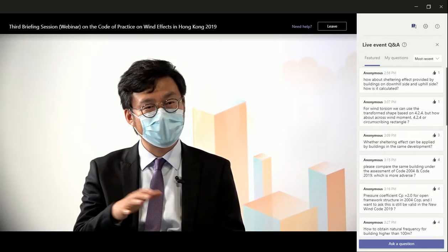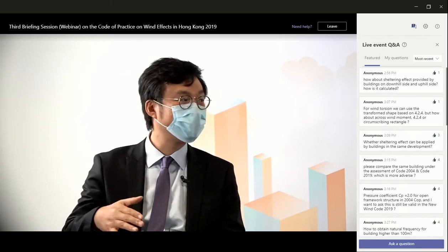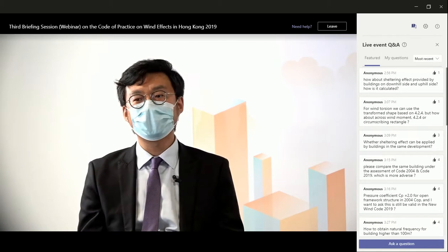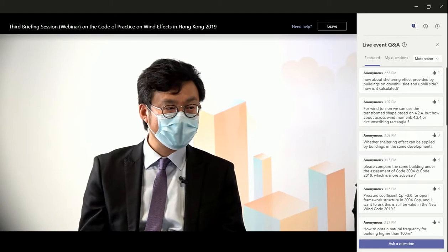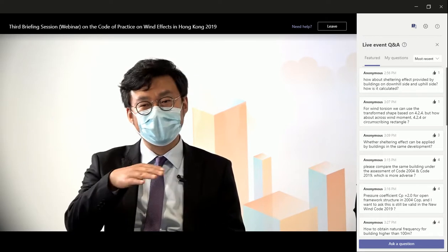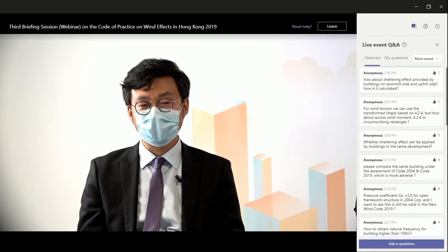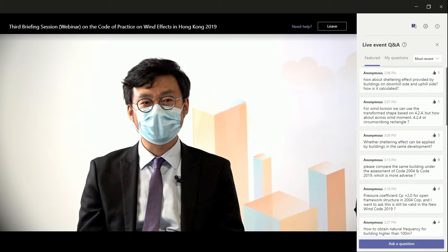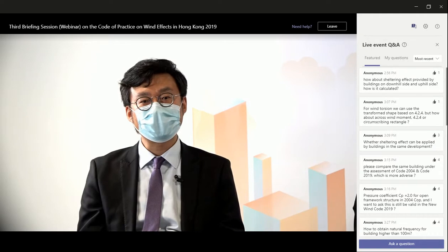Okay. So I think, thank you, Fion, for giving a constraint or a limitation. For this topic, as you mentioned, it's quite a broad topic. Following what Fion says, if we assume a scenario where, even though we have two diaphragms or split diaphragms, aerodynamically it is still one tower, then in this case we can still use our code to calculate the overall wind load, that is, the overall lateral force and the overall torsional force.